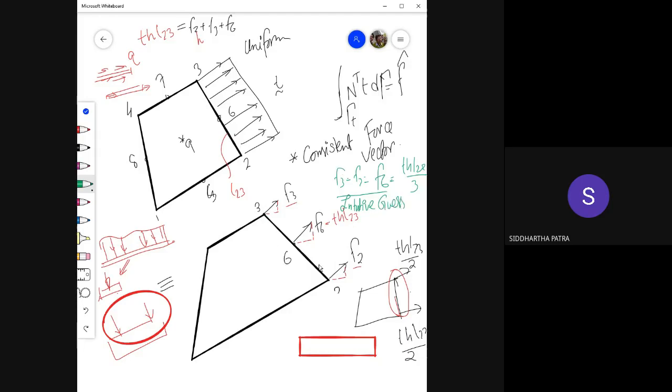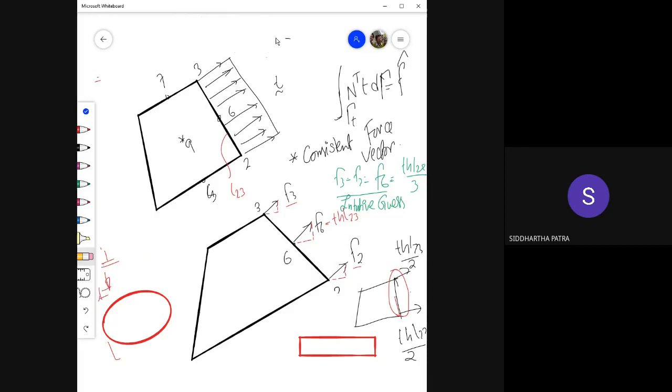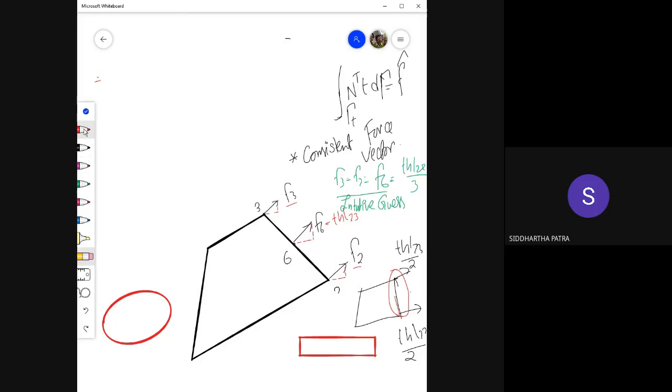Okay, so that is the guess we would make, because that's how we got equal values for the four noded quad element. But the thing is, in reality, since we are about to discuss a very different topic, we are kind of running out of time, so I'm not going into the derivation, but obviously you'll find the derivation in the notes. Okay, but I'll right away give you the solution. The solution is that the force would actually be divided in the ratio of 1:4:1.